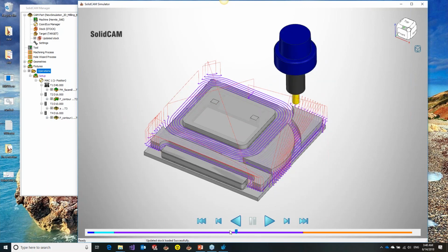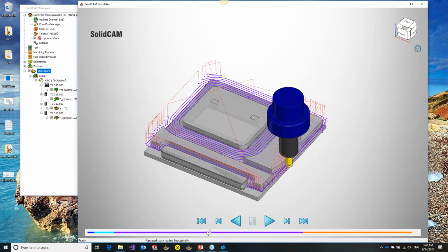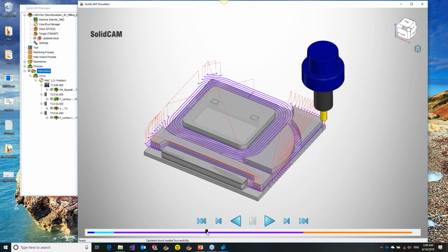So if you have a 2 channel machine, you'll see the toolpath on channel 1, you'll see the toolpath on channel 2 underneath of it, and the scroll bars will be synchronized, and you'll be able to do the simulation there. So that'll make it easier for people using channel synchronization, especially in Swiss screw and these areas. As you're developing toolpath, you can use this simulation, and then when you're ready to see full machine simulation and have real-time collision detection, then you can jump to machine simulation.